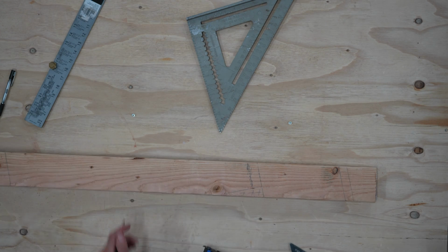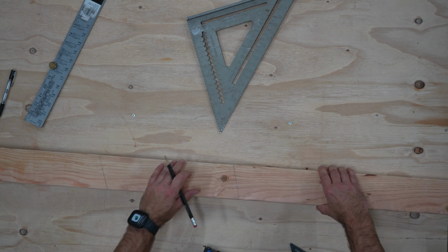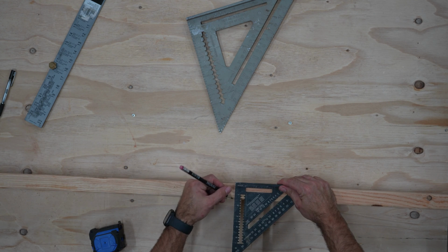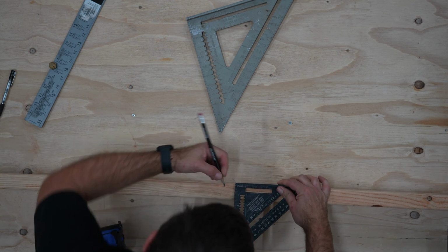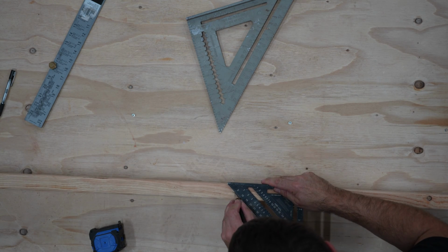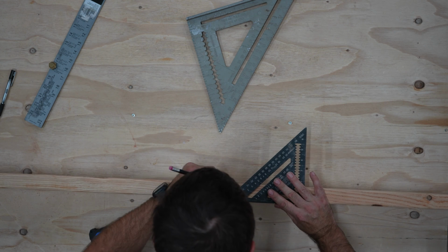Then I repeat this process on the other end. One thing you always want to make sure of when you cut rafters is that the plumb lines are all parallel with each other. If one looks like a backslash and the others look like a forward slash, something is wrong. This is a common mistake with new carpenters on the hip rafter, to make one of the plumb cuts going the wrong way,